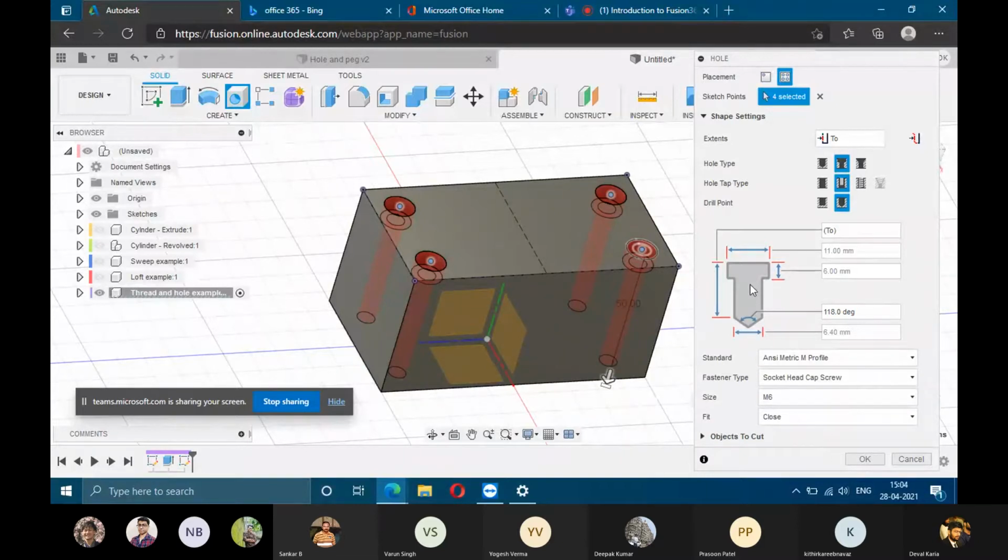because otherwise if you want to create a counter bore hole, you'll have to look for these dimensions from the standard ISO charts for screws, and then create 2 different extrusion commands, one for this and the next for the hole, right? So it makes the entire task very easy to do.